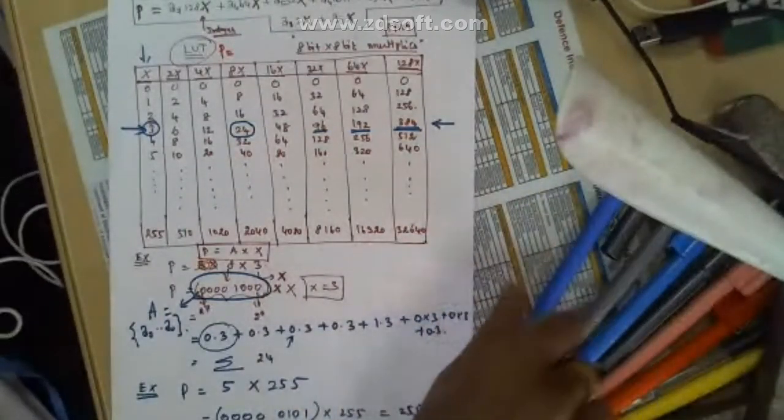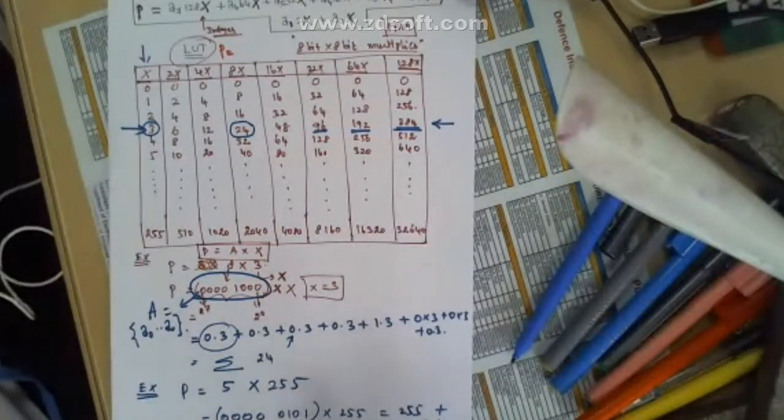So here addition is happening. In a fraction of a second, your multiplication will be over. You just need to pick up 2 or 3 elements based on the binary value and add them together. For addition, we are going to introduce the pipeline architecture, so that there is also high speed addition. That is why this structure, this algorithm, is called the fast array multiplier.